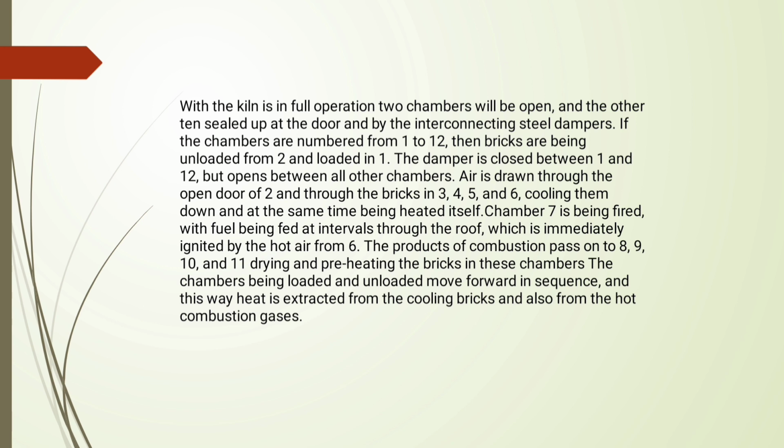Air is drawn through the open door of 2 and through the bricks in 3, 4, 5 and 6, cooling them down and at the same time being heated itself. Chamber 7 is being fired with fuel being fed at intervals through the roof, which is immediately ignited by the hot air from 6.